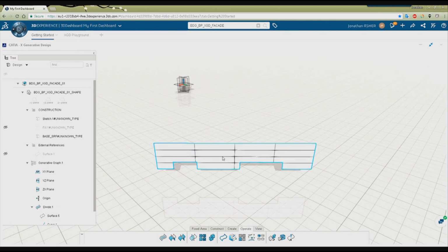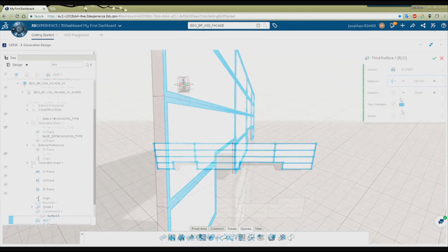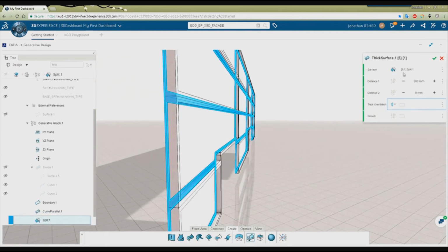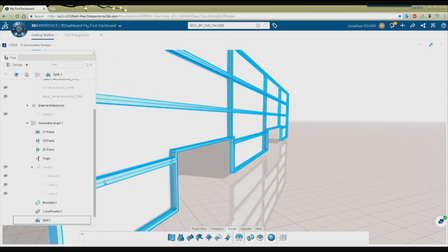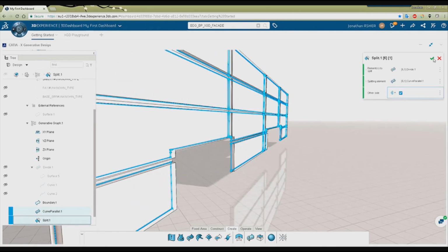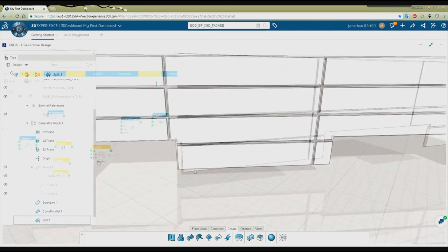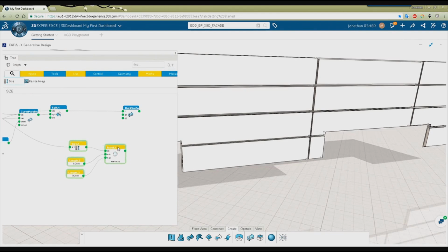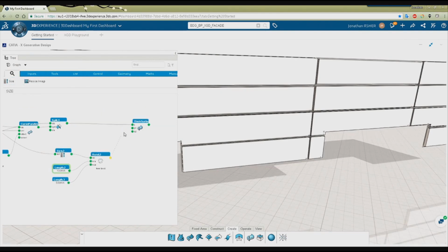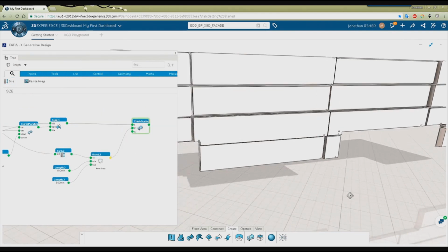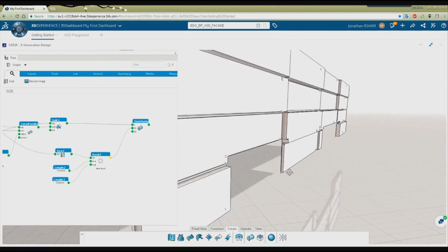We'll start by making a quick divide. We'll take the boundary curves of those divided elements. We'll offset those curves, and then we'll extrude those curves. We're doing all of this in the 3D immersive environment. At any point, once we're ready to modify the logic of our model, we can open up the graph. Here I've added a random value operator to produce variation within my model.